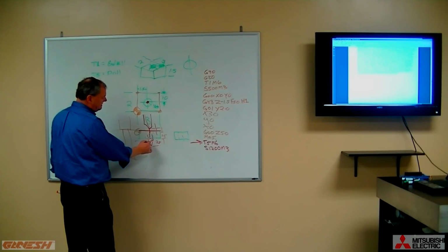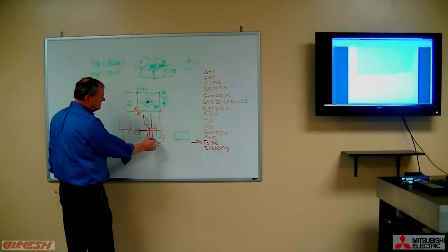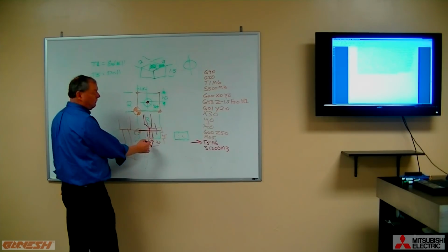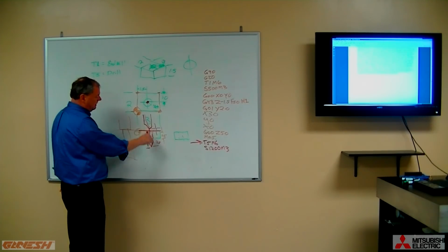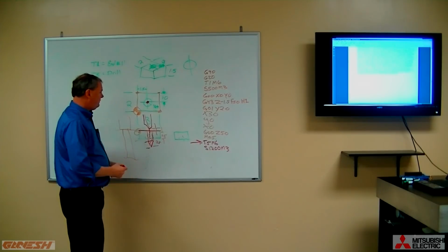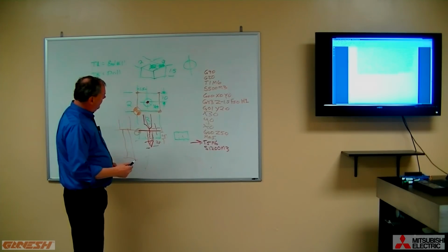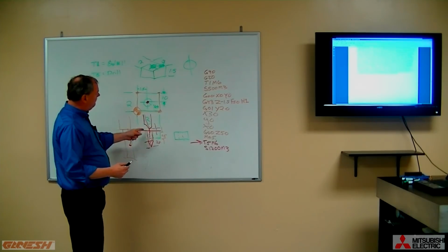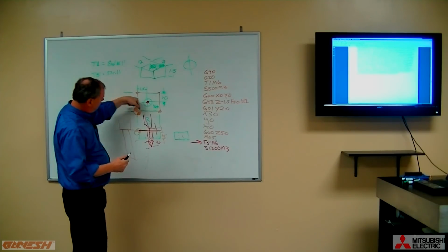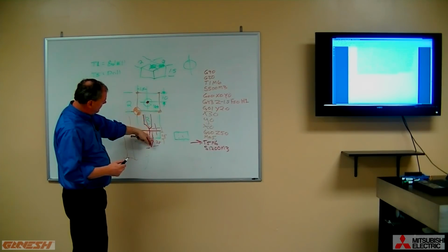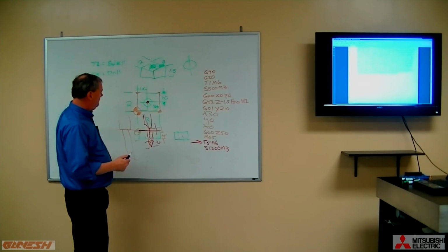Why? Because as you recall, our drills have a point, and we want to make sure that the hole is a ½ inch diameter all the way through. So we have to clear this drill point, this sharp point, through the part. And what we want to do, based on what you already know, how could you do this? Position, rapid, feed rate, rapid, and done.